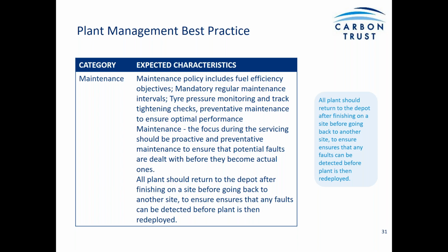The other thing is the movement of plant between sites. Very often the temptation is to just move it from one site directly to another, but best practice would obviously be sending it back to the depot to give it the once over, just to ensure that any ongoing or long-term faults can be rectified.